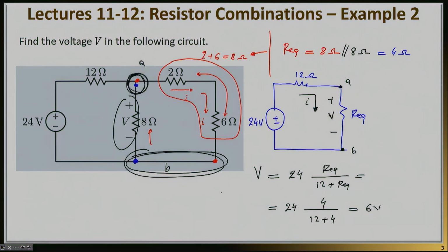So once again, I would like to emphasize that applying the voltage or the current division formulas is a great tool, and you should be utilizing it, but you need to make sure that the resistances are indeed in series or in parallel when you do so.